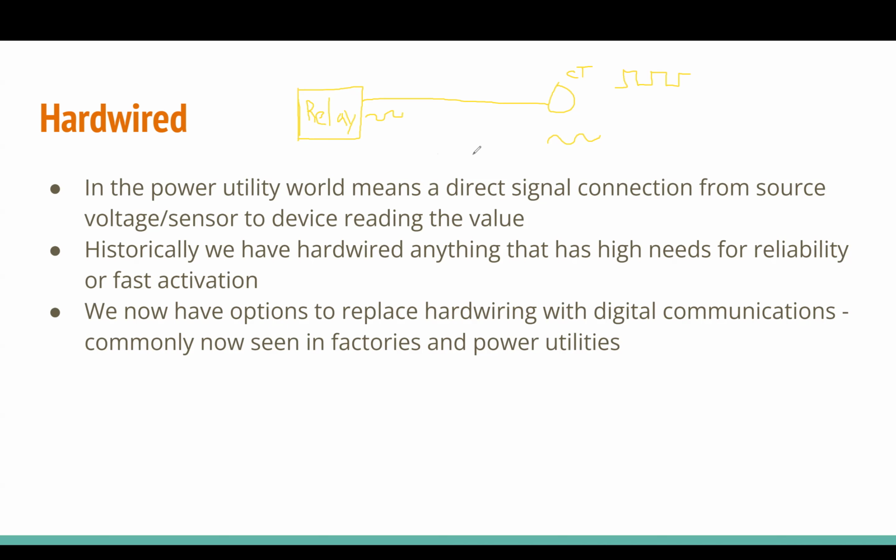Yes, definitely. So labor is going to be expensive because we already have these systems up and running. And so if you want to convert it from what it was hardwired into a SCADA situation, you need to tear it all out, convert it into digital and everything, run new cabling. So if it's already working hardwired, why would you do that? There are benefits theoretically to going into the SCADA world, but for right now, what we're doing is working hardwired.